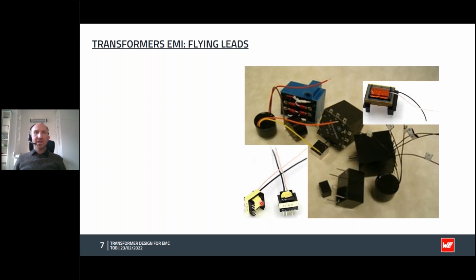But on the secondary side, we've wound, usually we'll wind with some safety wire, insulated wire. Triple insulated wire would be an example, or FIW is another example. This is special safety wire, which has a high voltage rating and is approved for safety. So we don't actually need to meet any distance between the primary and this wire itself.